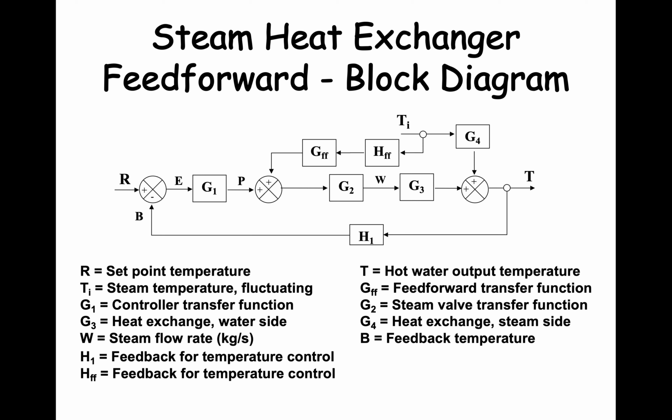So let's see what happens if we add feed-forward control. We are interested in adding feed-forward control because the steam temperature fluctuates. In the earlier sketch, we added a temperature sensor upstream of the steam flow valve.